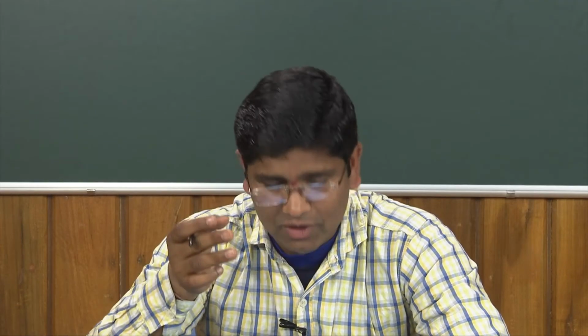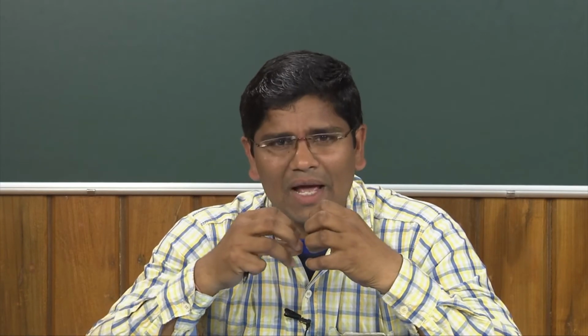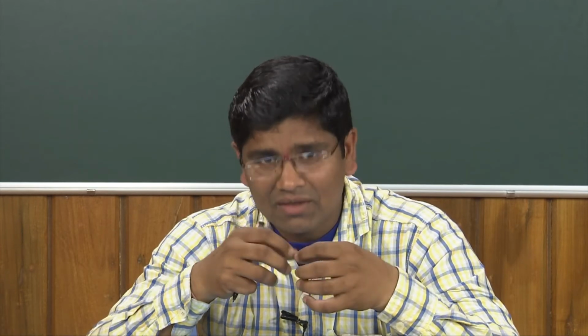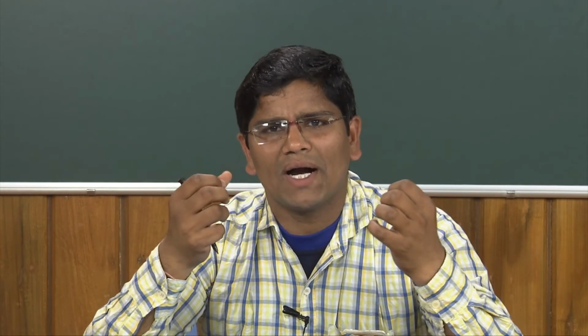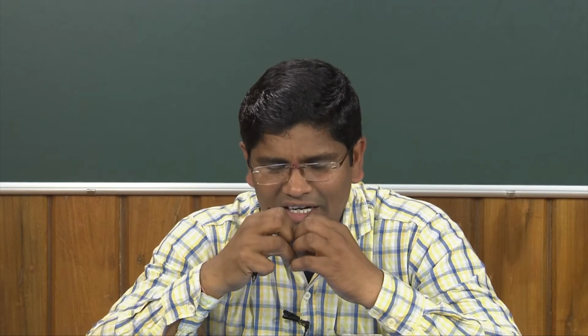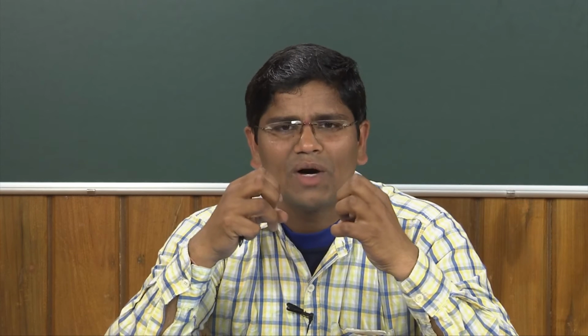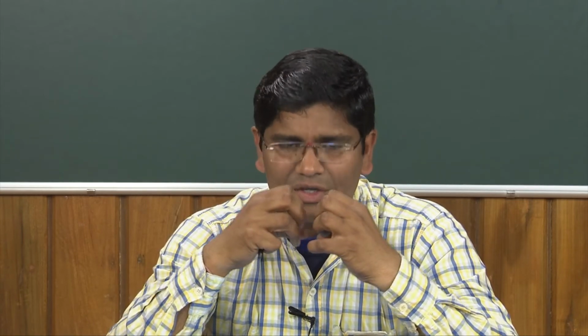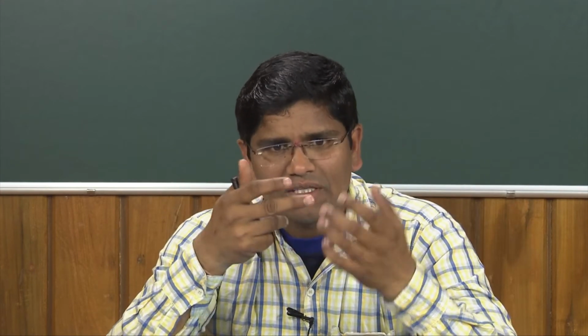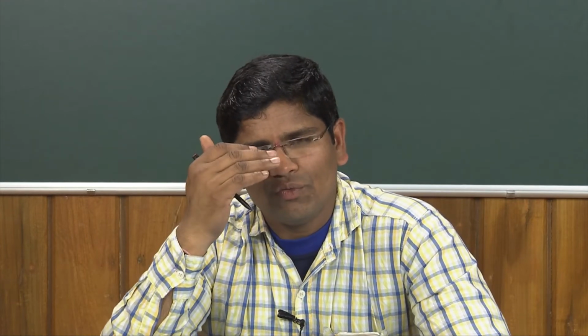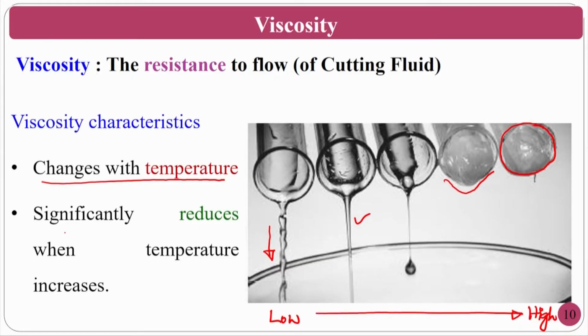Most of the cutting fluids will change with respect to temperature. As the temperature goes up in the cutting fluid, what will happen? The molecules gain energy, which is called thermal energy, and they try to move apart. That is why the cutting fluid fumes go to the operator's nose. It gains energy and the molecules move apart, the distance between two molecules gradually increases, and the force of attraction between them goes down as the distance increases. That is why mostly the cutting fluid's viscosity will decrease with respect to temperature. The viscosity significantly reduces when the temperature increases. As the temperature increases, the intermolecular distance increases, so the intermolecular force of attraction will decrease, and that is why the liquid becomes gas and it flows.